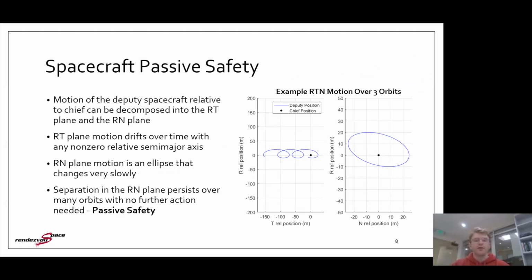And so this is the notion of passive safety I briefly mentioned before. When we say we want an orbit to be in a passively safe state, we want it to need no further active inputs in order to avoid a collision. So if our 2 spacecraft are facing an impending collision, they'll need some sort of action, and then after that action, the spacecraft don't have to make active choices after that point. They'll be in a state where they can basically say, I'll be safe over the next horizon and I'll have time to diagnose and figure out what's going on.